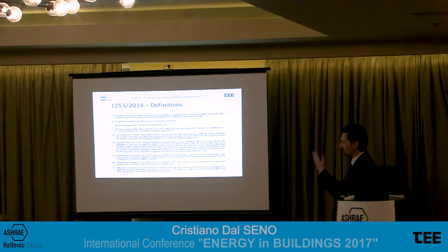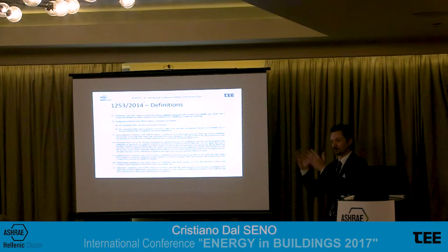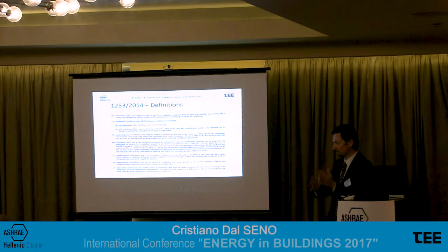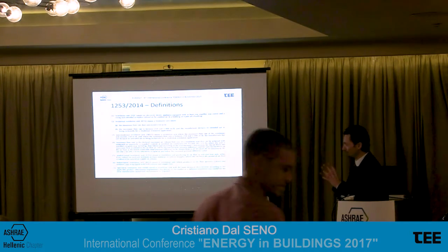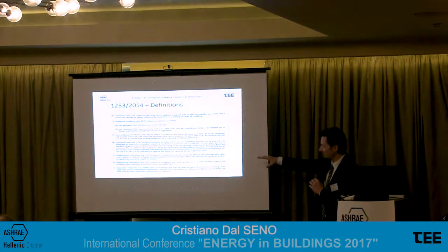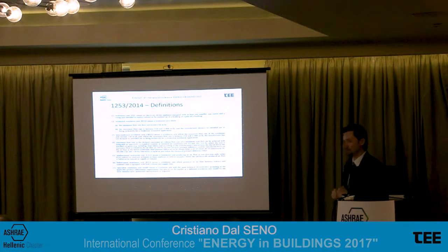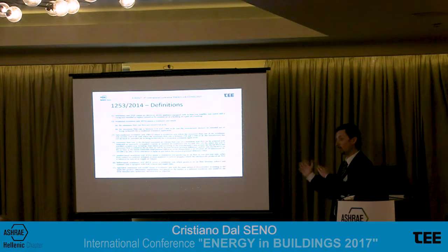Then the regulation gave the definition of what is a ventilation efficiency, of what is a heat recovery efficiency, of what is a heat recovery system. So we have all the definitions within. But these are definitions that we usually integrate in our daily job. So it is mainly important to make this differentiation between bidirectional and unidirectional ventilation units, because it splits the calculation to be applied when we design an air handling unit: one way to calculate unidirectional ventilation units and another way for the bidirectional ones.